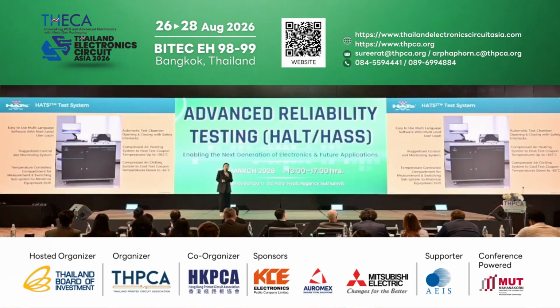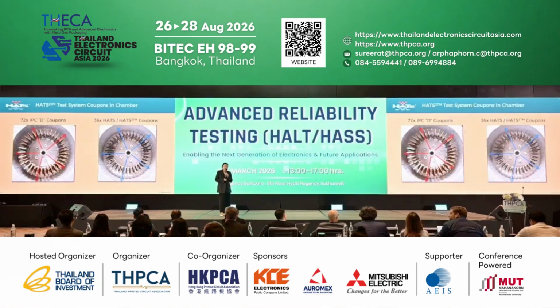The machine itself uses compressed air to heat and cool the coupons inside. It doesn't need any additional special air, special electrical, or heating tool. It also has very accurate flow control to get all the air past the coupons evenly. In one chamber, the system itself can test 72 IPCD coupons, as you can see on the left side of the slide, and 36 HATS or HATS2 coupons.